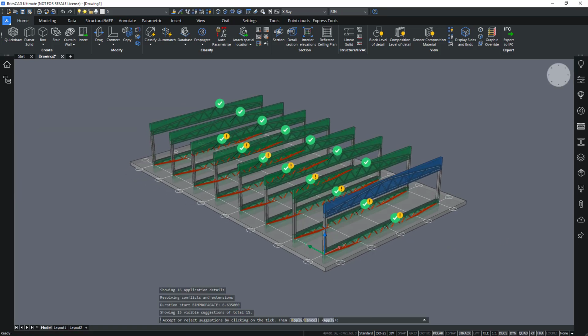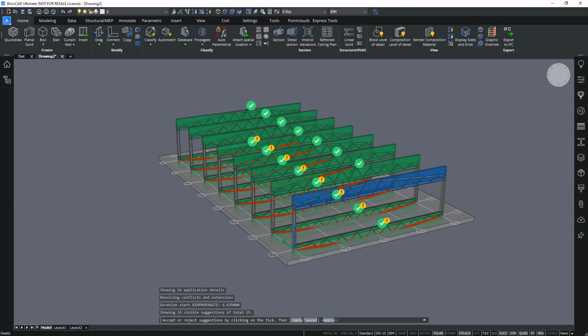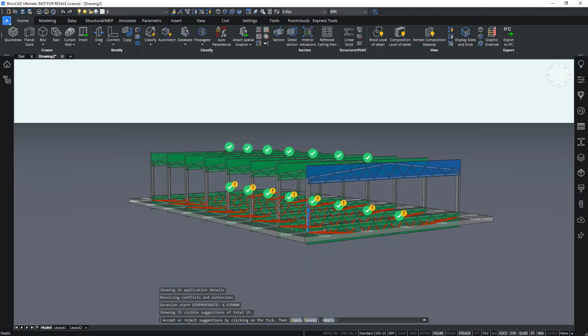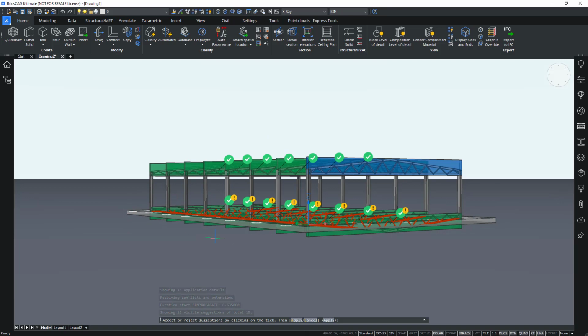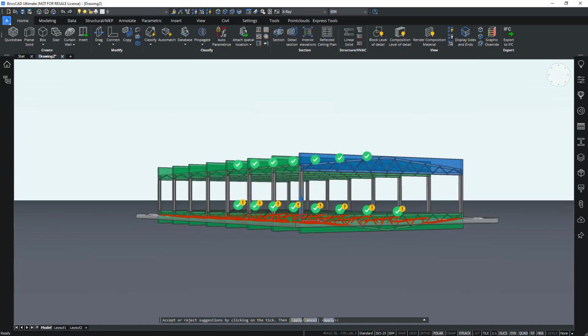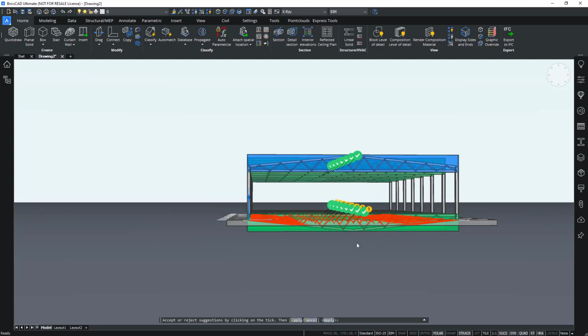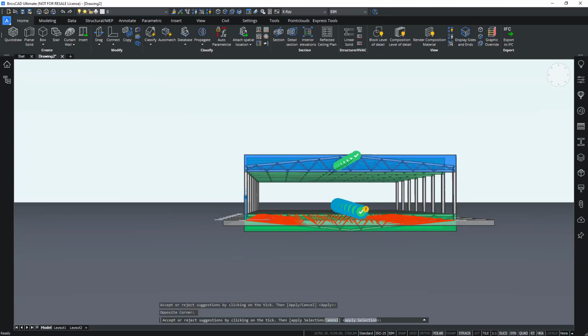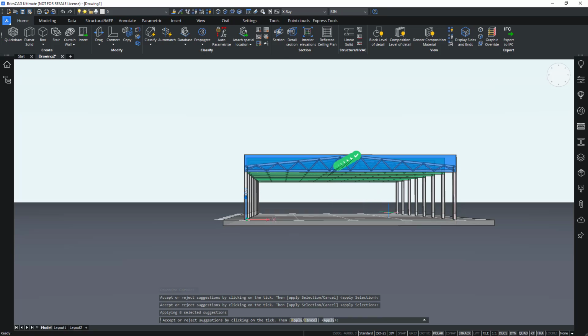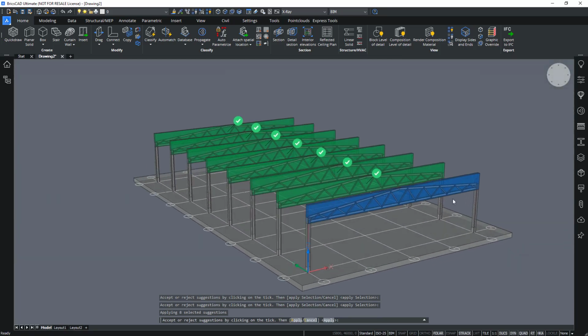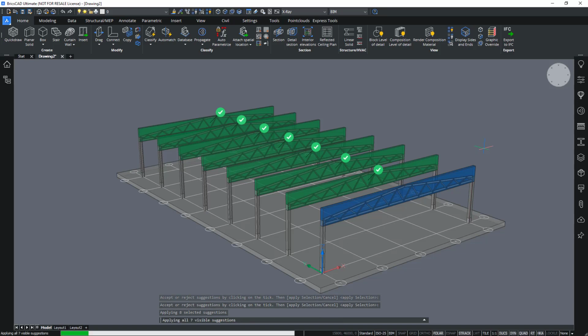15 suggestions. As you can see, it finds suggestions not only here at the top, but also at the bottom, because the two columns are symmetrical top and bottom. So it finds similar locations at the bottom here as well. So let's just select all of these suggestions here and turn them off. And all of the others we will enable.